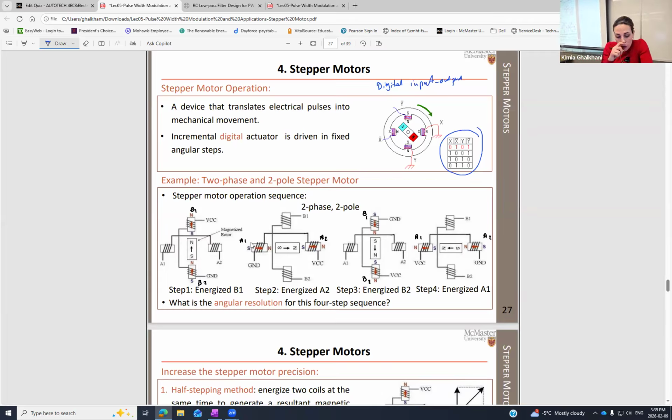So we can simply use it for any application that controls signals as a digital pulse. But remember, for the DC motor, last week I said, DC motor by default is not digital, it's analog. But here by default it is just digital. So one digital pulse to a stepper motor divides the rotation. Sometimes you have it as a larger size, which simply means you can see the operation principle of two-phase.